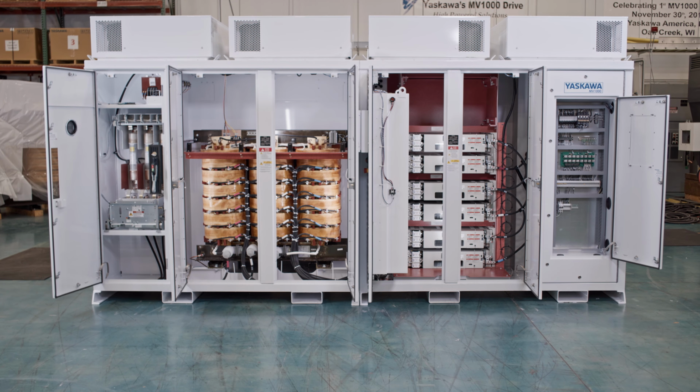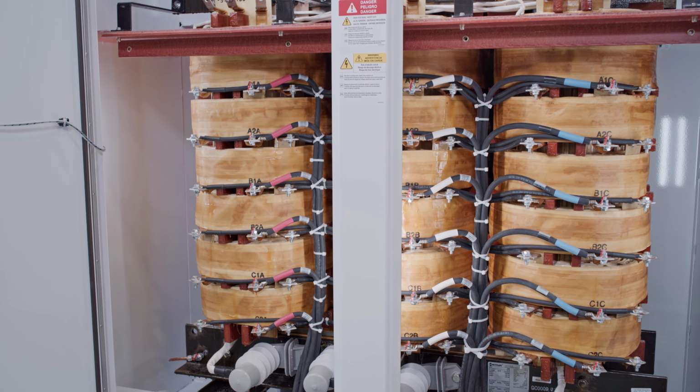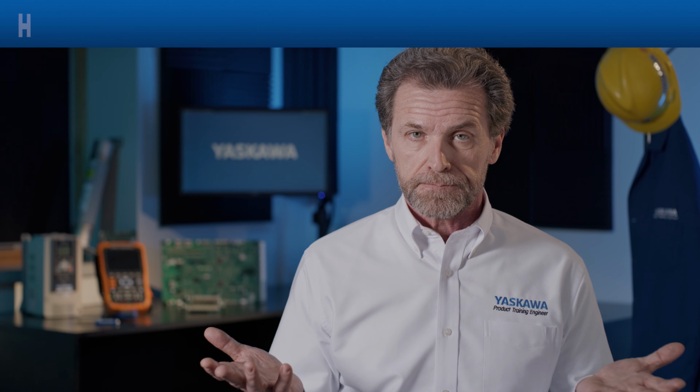Well, we've explored how multi-level MV drive topology can improve system performance and reliability by improving the motor output waveform. So now, let's look at how choosing an MV topology can improve system input power quality. MV smart harmonic technology can be utilized to nearly eliminate the concerns of total harmonic distortion, or THD, present in 3-level drive topologies. What is harmonic current and where does it come from?